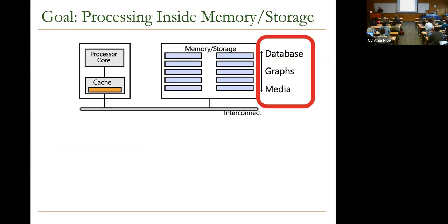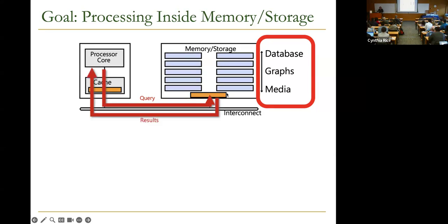Essentially, we have applications stored in memory. And for the processor, we're going to use an accelerator model, in a more futuristic incarnation of this sort of idea. Everything is a distributed agent, basically. There's no processor, in a sense. There's no master. Everything is really doing operations, and then you're coordinating. So it's a distributed system. But now we're going to suppose that the processor is offloading some computation to memory, asking the question, memory, can you do this operation for me? And the memory returns the results. So the data doesn't move, but the function moves from the processor to the memory device.